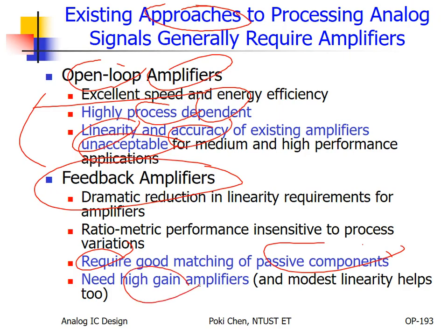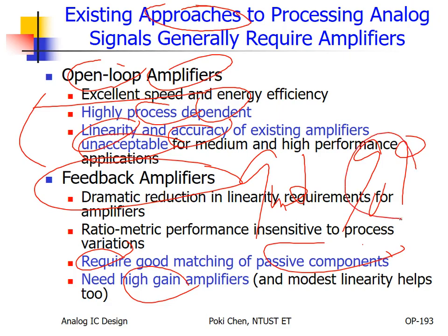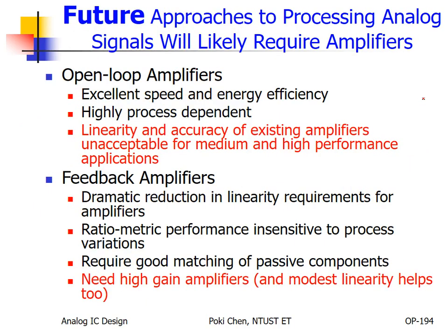But I told you already, with new processes, the GM is reduced according to early saturation. And the GO is increased according to leakage. Because the gate oxide becomes thinner and thinner, right? It is not isolated anymore from your channel. It is leaking. Leaking means more conductivity, or it means RO is reduced substantially. So it's really bad.